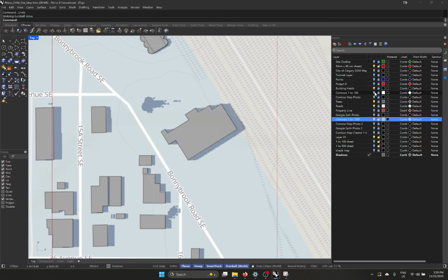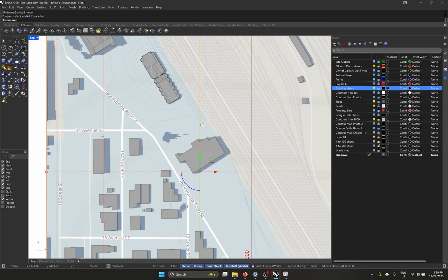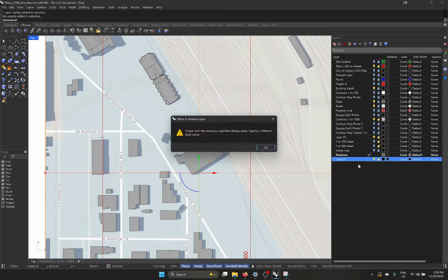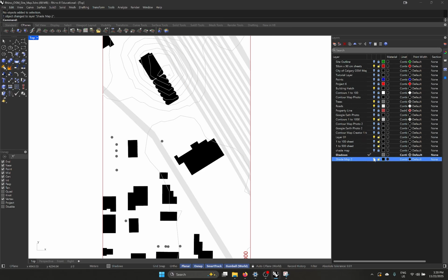So the next step there is we can have our building hatches shown. And how we could do that is we could select all our building hatches. So these, like if I show here, if I create a layer for the shade map, and then right click it, change object layer, I can turn it off and I can see how it's pretty well aligned, right? But what I might want to do is go to all my buildings, hatches here.